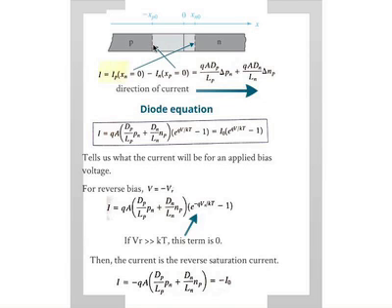Okay, and in reality, if you want to calculate current in a device, the current is constant throughout the device. That's the assumption. So if I calculate current at this location or this location or this location, they should all be the same. But my assumption here is that I will calculate the electron diffusion current here, the hole diffusion current here, and the hole diffusion current here is the same as the hole diffusion current there. So I can just add these two up. You need to go back and think about that. It's a little bit of an abstract concept.